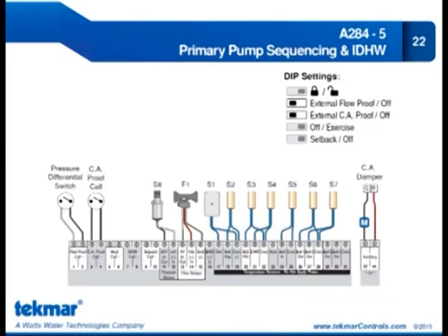Yes, because we have multiple sensor inputs, S1 through 7. That's correct. I'm just saying, if we brought that temperature in, we wouldn't be controlling it, but maybe it would be visible through another temperature sensor input. Well, if we're not using all the temperature sensors, 1 through 7, right? What if we decided to use one of them for that low temperature that we wanted to make visible on the BAS? That way it would still be coming into the 284.